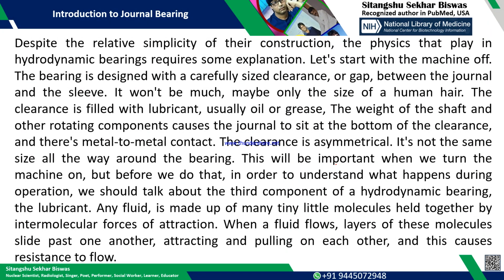So when the motor is on, what is the mechanism or component responsible for the bearing action, lifting up the entire shaft? In this aspect, the fluid plays the major role, and one parameter is very important, which is the viscosity of the lubricant or the liquid.